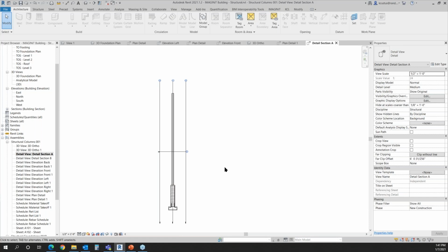Maybe you have a portion of the building that you're collaborating with and you want to send just the documentation to one firm, create an assembly. Use that documentation as opposed to your regular construction documentation. Okay. So those are the benefits of assemblies. Okay, much better to use than groups. You have a little more accessibility to the view, and you have views that you can actually look at as opposed to groups when you have to actually pull it into the project and somehow visualize it.